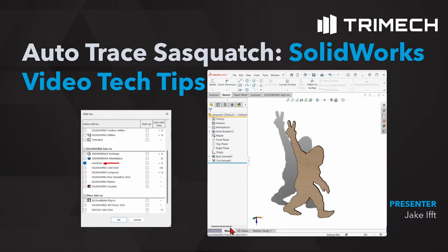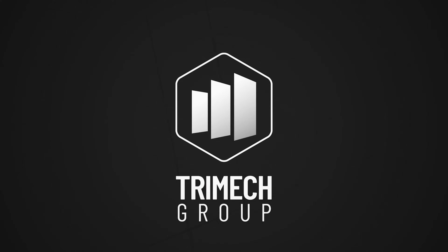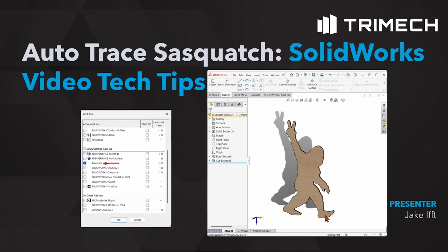Have you ever wanted to take a picture, maybe some kind of silhouette of a logo or some kind of image, like this Sasquatch here, and turn it into something that we could make using SolidWorks? If we use the sketch picture command, along with the Autotrace add-in, we can turn some kind of screenshot into lines in a sketch that we can use to manufacture a real-world object.